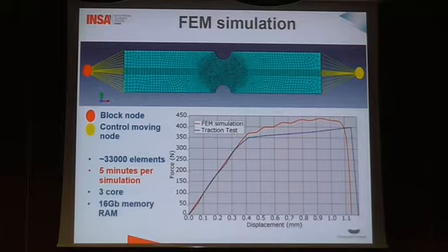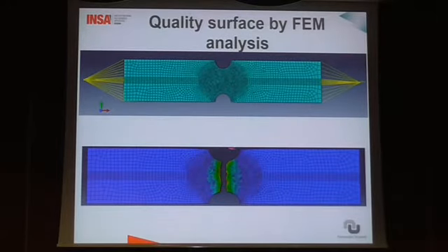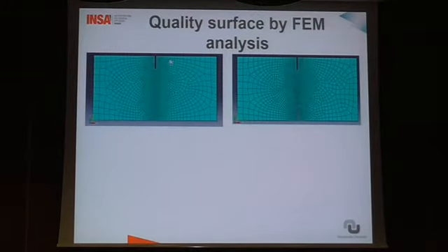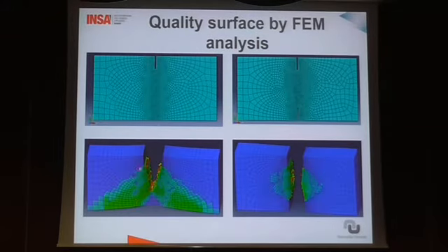our model, first we fit the force and the displacement on the specimen, and then we fit the quality of the surface. When we are happy with our results, we can change the geometry. In this case, we change the geometry with 1 pre-deformation and 2 pre-deformations. We can see on the left the fracture has a linear propagation, but on the right we have a curved propagation.